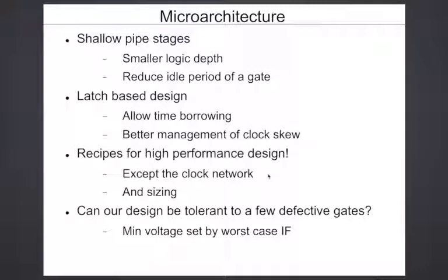And the art of this is to do it reasonably accurately, but without having to do the complete design and then come to a realization that this is how you should have done it, right? That only comes with experience. There's no formula you can plug in that will tell you the number of pipe stages. This is the engineering you have to do. When you're designing your chip, these are some of the trade-offs you have to work out and figure out how to handle.